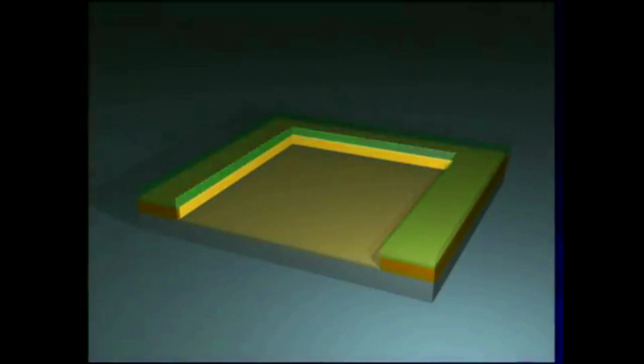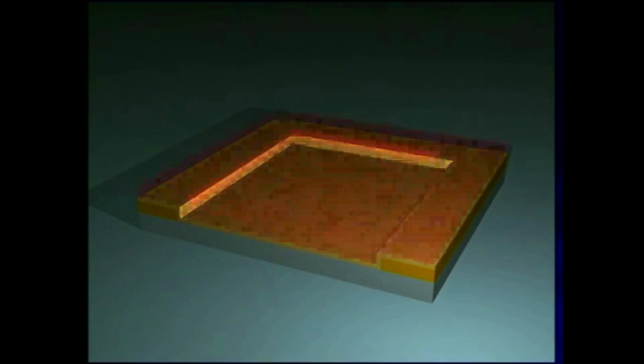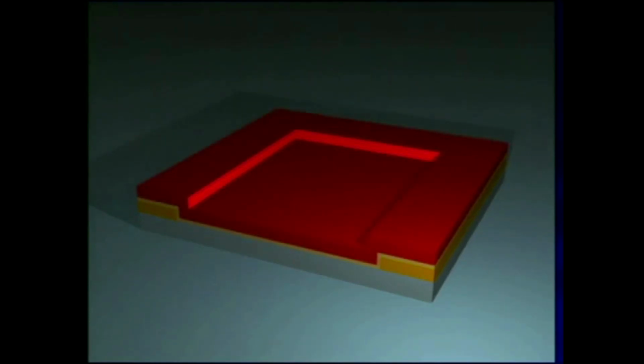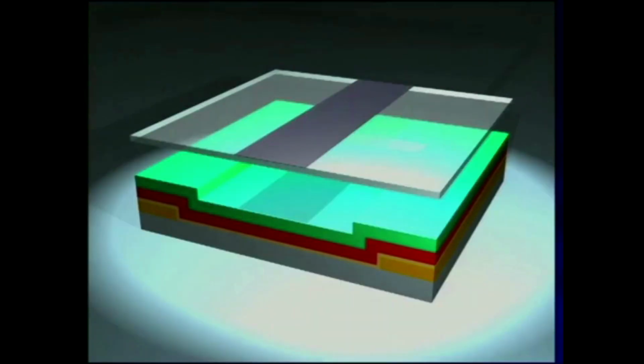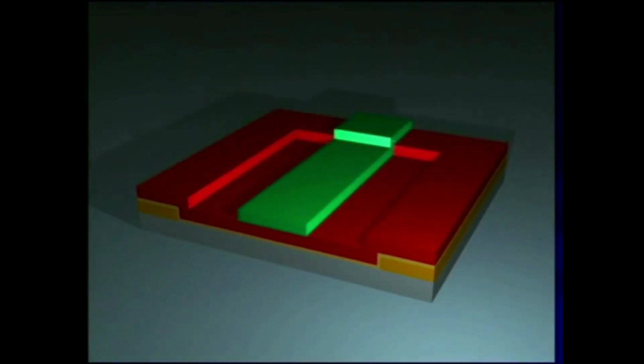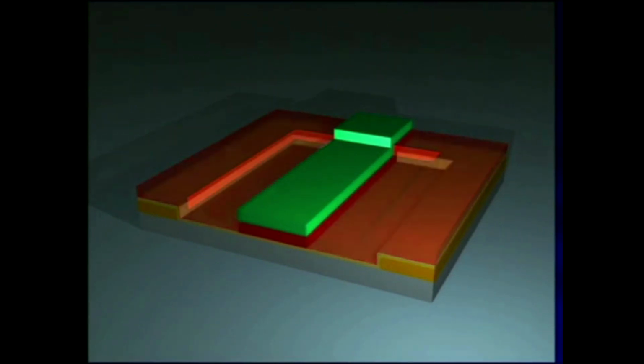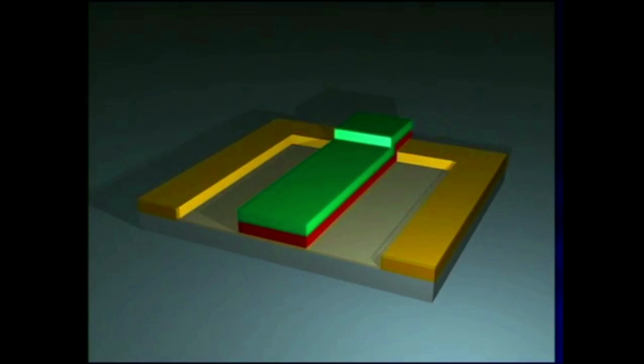After dissolving the remaining photoresist and then cleansing, another oxidation takes place. This time a very thin layer is affected. Electrically conductive polysilicon is deposited on this insulation layer. Then once again photoresist mask and exposure occur and the exposed photoresist is again dissolved. Then the polysilicon and the thin oxide layer are etched off; they both remain intact only in the middle under the resist layer.